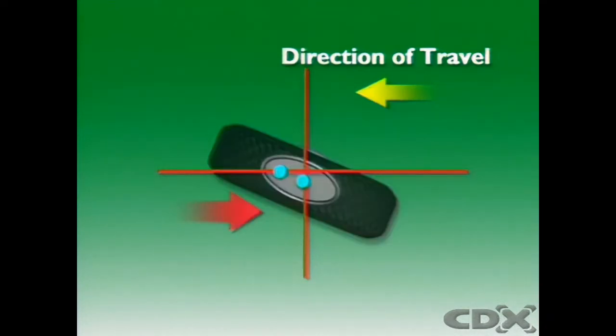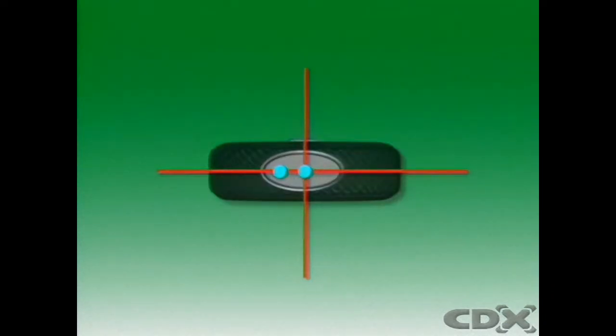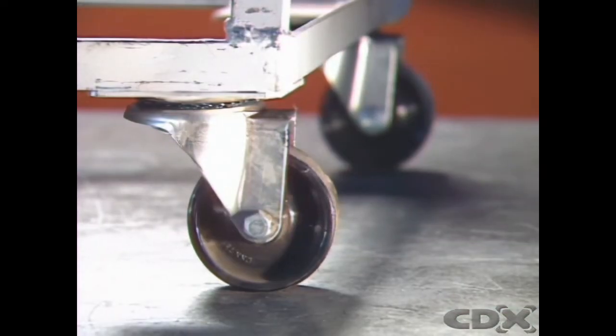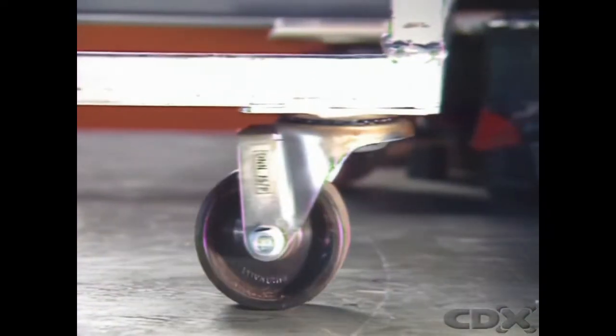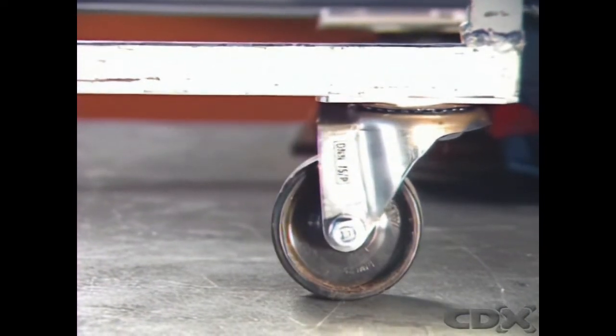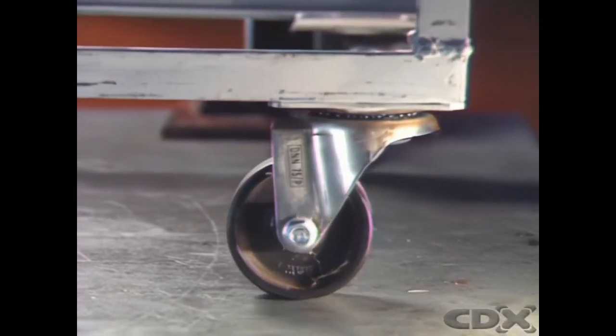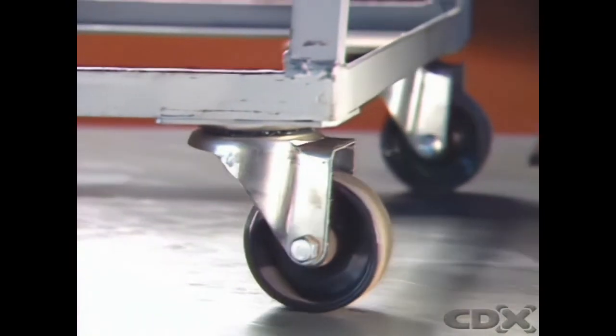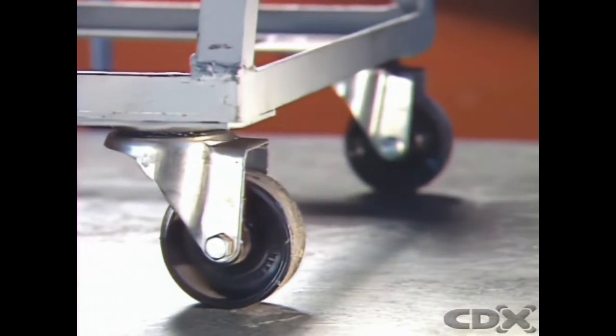In forward motion, this generates a self-centering force which helps return the wheels to the neutral position when the steering wheel is released. The effects of positive caster can be seen in the motion of this furniture wheel. When it is acted on by a forward-moving force, its pivot point ahead of the wheel ensures the wheel always trails behind.